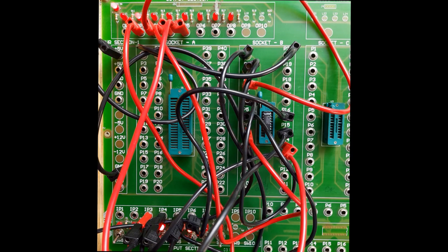So in this way you can verify all the input combinations in the given truth table for binary to gray code conversion. Now we'll see the next part, that is gray to binary code conversion.